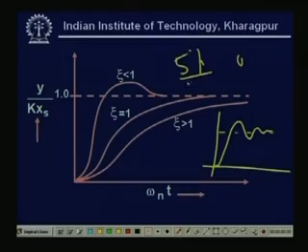But in some processes, especially in bioprocesses, you will find the precision, the temperature, should be very tightly controlled. So a 5% tolerance cannot be allowed there, because cells will die in those cases. Suppose the temperature is 31 degrees centigrade, I have to maintain it exactly at 31 degrees centigrade, or it might be only 30.5 to 31.5. If the temperature goes beyond that range, cells will die. In those situations, I cannot allow this 5% tolerance band.